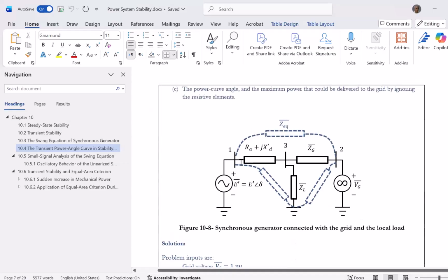This impedance, as you can see, is not a direct impedance. What we mean by direct impedance would be something like Z equivalent, which can be found by transforming this Y into an equivalent delta, right? If we transform this Y system into a delta system, then we would be able to find that direct impedance, which is Z equivalent.